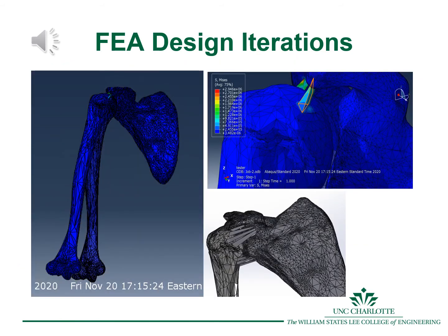Our final design included lofted connections to act as ligaments. Previously we were using beam elements, but these 3D models work better. The lofts simply provide a connection between two faces on different models. We were able to set the model up in Abaqus to run jobs. Boundary conditions were applied to the right side of the scapula.